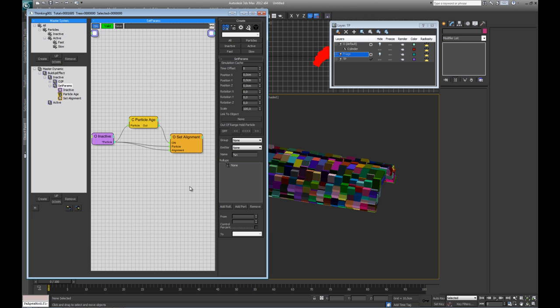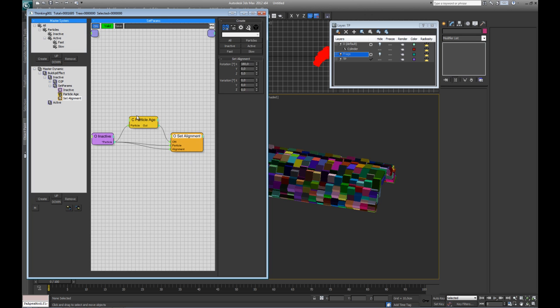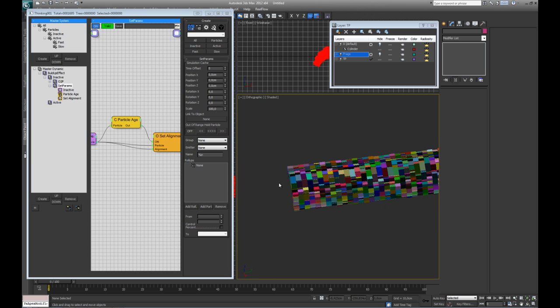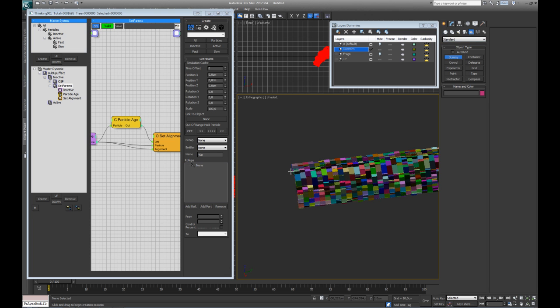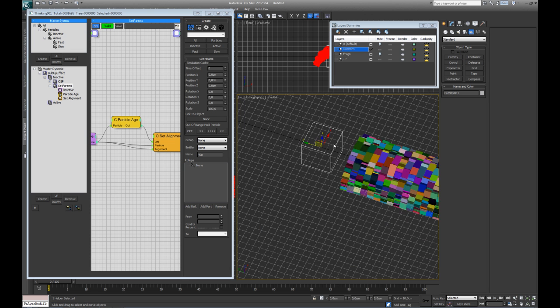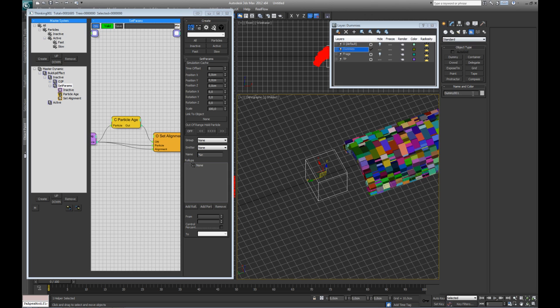Anyways, so the next thing when this is done is to activate these, and for this we have to get a dummy inside. This is actually activated using a distance, so I'm gonna create a new layer, and I'm gonna call this dummies. This is because in big scenes you might have a lot of dummies, so I like to again use the layer system to keep my scene clean. I'm gonna create a dummy, and from the top view I'm just gonna drag it out like this. The dimensions don't really matter for this, it's just so it's easy to spot. And I'm gonna call this the target.